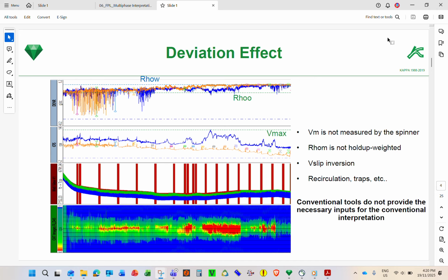Yeah, this is the capacitance array. So you have 12 lines, which is 12 sensors. So 0 means gas, 0.2 is oil, which is the green. Blue one, 1, is water. So you can have 3 phase. The capacitance, as I mentioned, you can only have hydrocarbon and water, right? But in the 3-phase condition, it can be used for 3-phase because you have water, oil, gas.